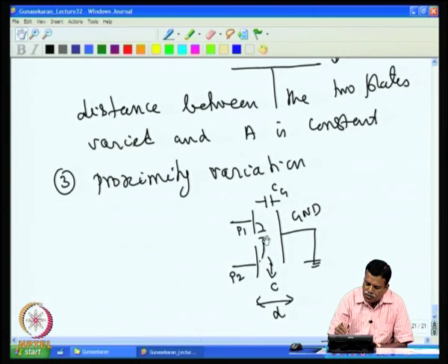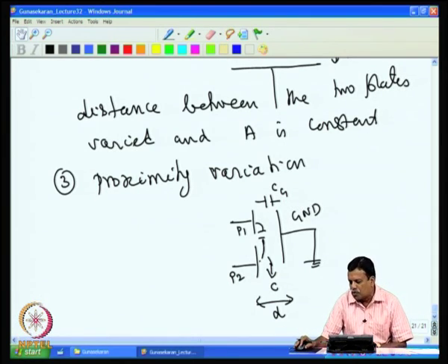If I come closer and closer, you find that this capacitance is decreasing, and as I move more away, this capacitance is increasing. So, this also can be used to sense the displacement.